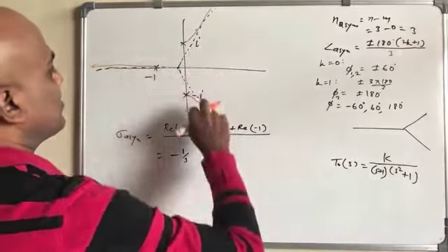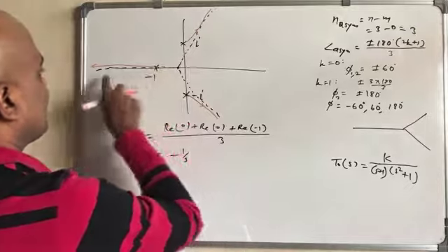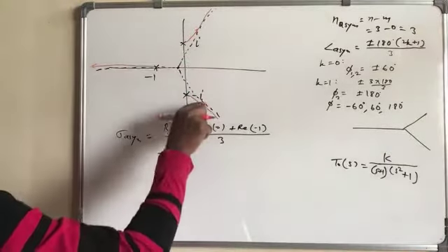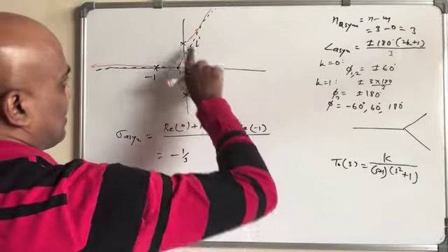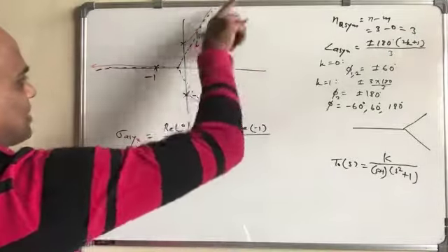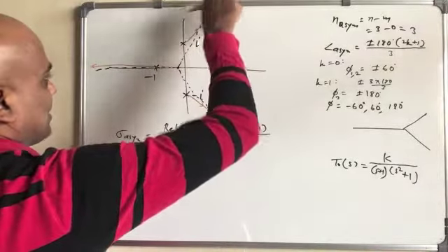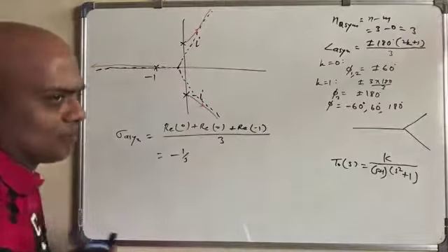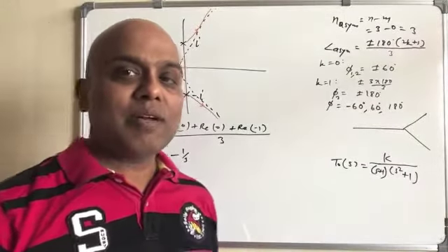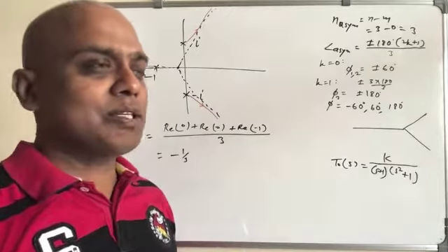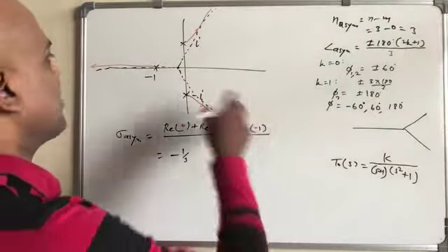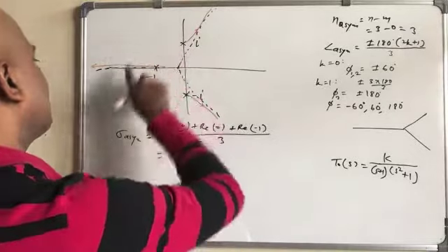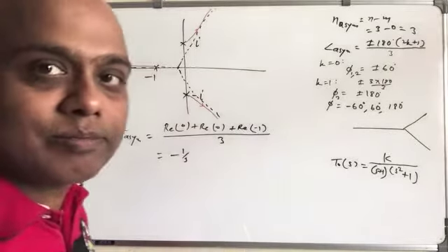There are 3 asymptotes, you see, and all of them originate from the poles in this example and go to infinity, because there are 3 zeros at infinity. So the number of zeros at infinity is equal to n minus m. Since n minus m also tells you the number of asymptotes, it gives you 3, and it goes like this.